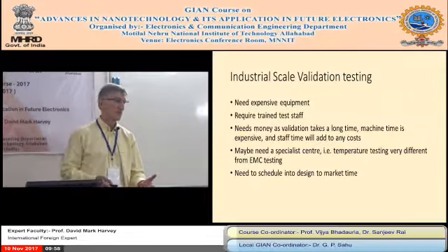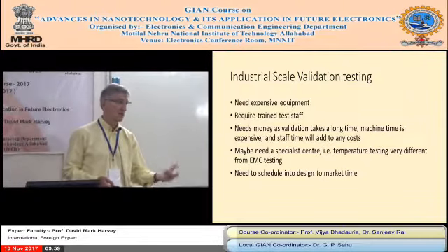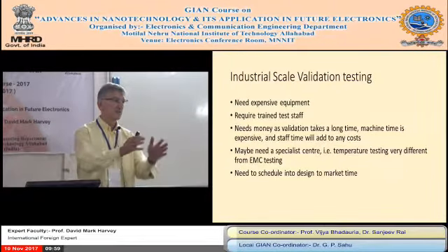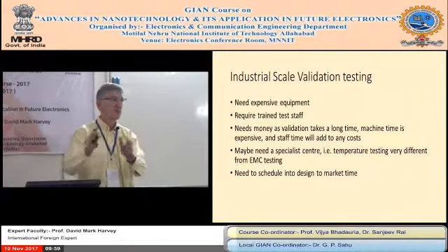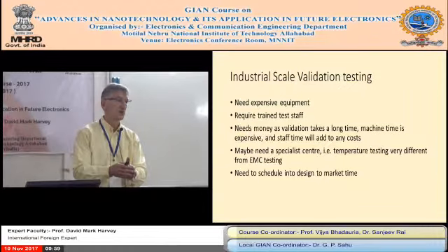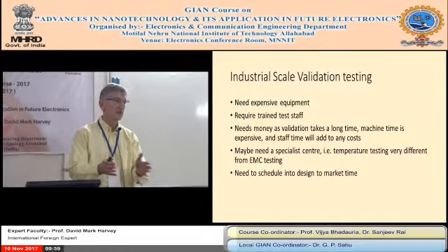And you might be quick at designing circuits. Doesn't matter if it's a chip, a circuit board, or a whole system. Say you think, oh, I can design that in 2 weeks. But to do validation testing might take 2 months. So if your boss says, when can we release this product, you have to factor in design time, test time, and validation time, which a lot of people, when you're starting out, wouldn't know to do. If you launch it without validating the products, it can be done, but it's risky.